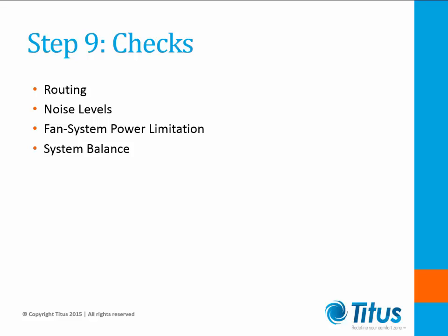When system resistance is calculated, a fan selection can be made. Make sure to include pressure drop for filters and any intake louvers. Both the supply and the return air pass all the way back to the equipment. Verify selected fan and motor are in compliance with the local energy requirements. If the fan power is out of compliance, it will require ductwork redesign to lower your pressure drop of the system. Review system balance, making any final changes to provide an approximately balanced pressure loss through all branches.